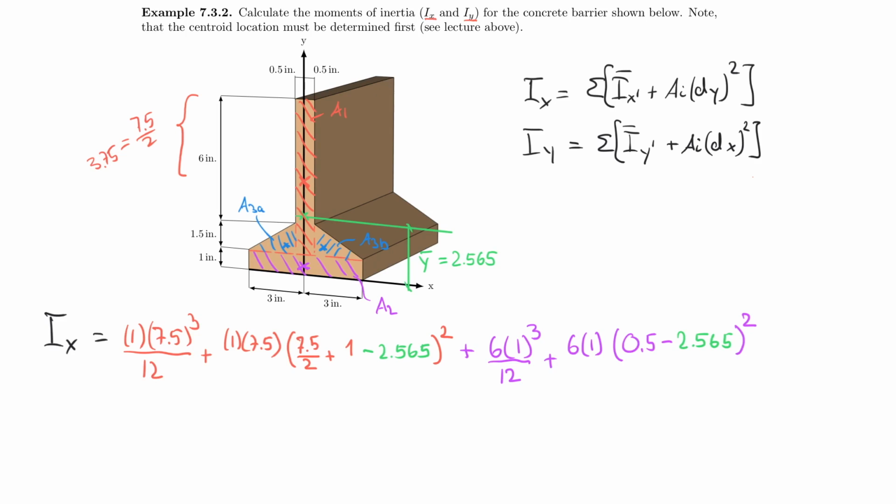Okay, now we can use our A3A. And what is that? So now we're using a rectangle, sorry, not a rectangle anymore, but a triangle. So what is it? Base times height cubed divided by 36, right?